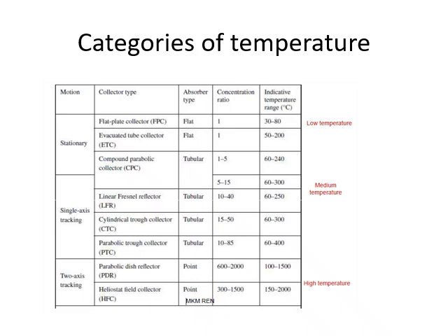We will be focusing mostly on the concentrating solar energy technologies. The solar concentrator, or concentrated solar power, whichever way you want to name it, is categorized based on the required temperature. For low temperature applications, we really do not want to go for concentrating techniques because they are expensive. It will mostly start from medium temperature to high temperature. The medium temperature range is somewhere between 60 and 250 degrees Celsius, and the high temperature can reach up to 700, 800, even 2000 degrees Celsius.